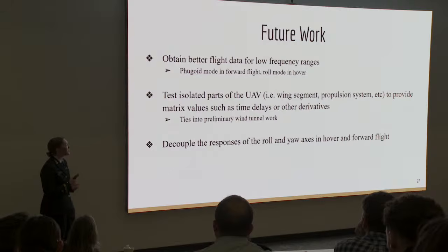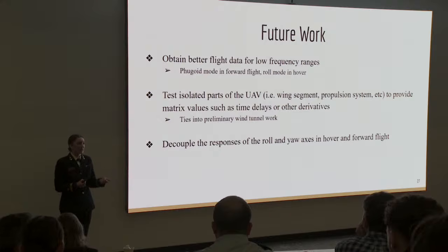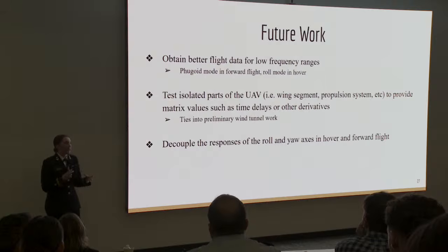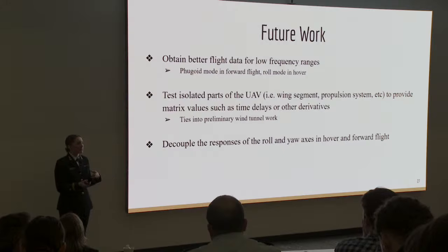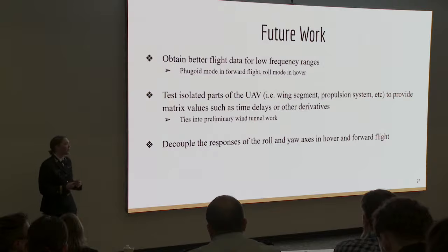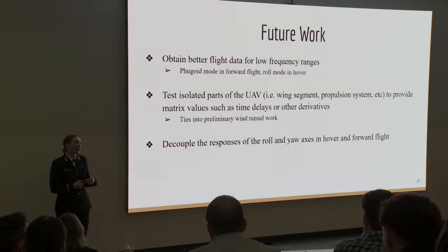low-frequency modes. Additionally, we can test isolated parts of the UAV, whether this is a wing in the wind tunnel or just a thrust stand, to isolate some of the control derivatives and time delays. And if we can fix those values in the parameter matrices in our state space model, that's less iteration that the software has to run, and so it can help make the other values more accurate as well if we fix those beforehand. Finally, we could also look into decoupling the responses of roll and yaw axes in hover and